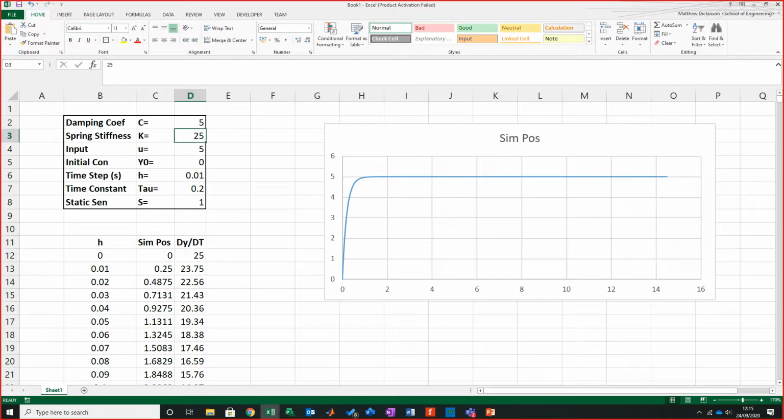That's much better. So in any spring state, if we make it much greater, if we go 45, the spring slams shut, as you'd imagine. The damper can no longer do its job, it can no longer support the output that it's been given. But if I then make it close to the damper, if I drop it to a strength of 6, what we see now is, if you look at the response, it's almost in the arc format. The response itself, there's a very linear response to it. That would imply that the damper is dissipating the force incredibly well.